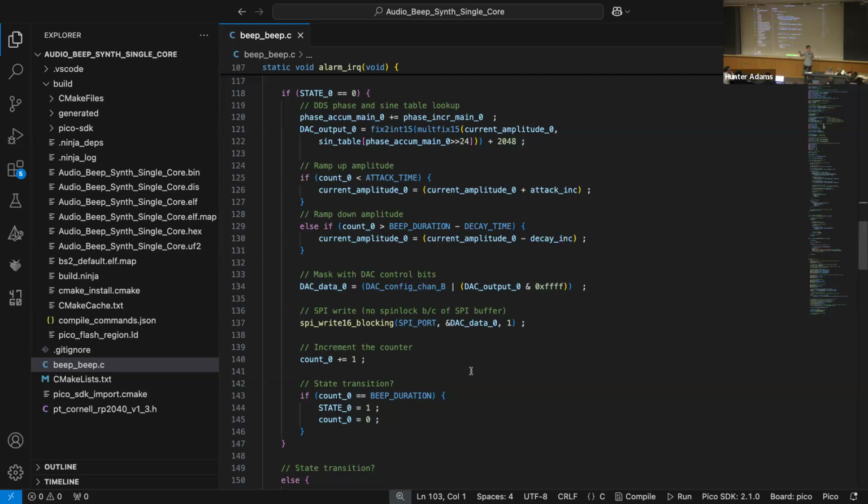You hear them all at once, sounds like a click. A more physical mental model for this is the voltage that we're sending the DAC specifies the position of a physical membrane in the speaker. If that membrane's at rest and then you suddenly go full amplitude, it's going to go boing, boing, boing, boing, like this, right? Because it's a physical system. That boinging contains all those high frequency sine waves that I was talking about, and it sounds like a click.